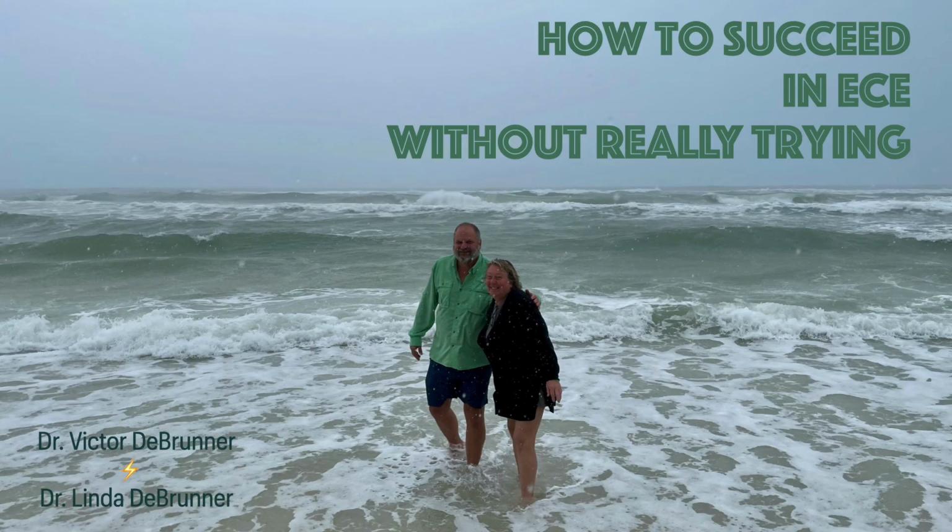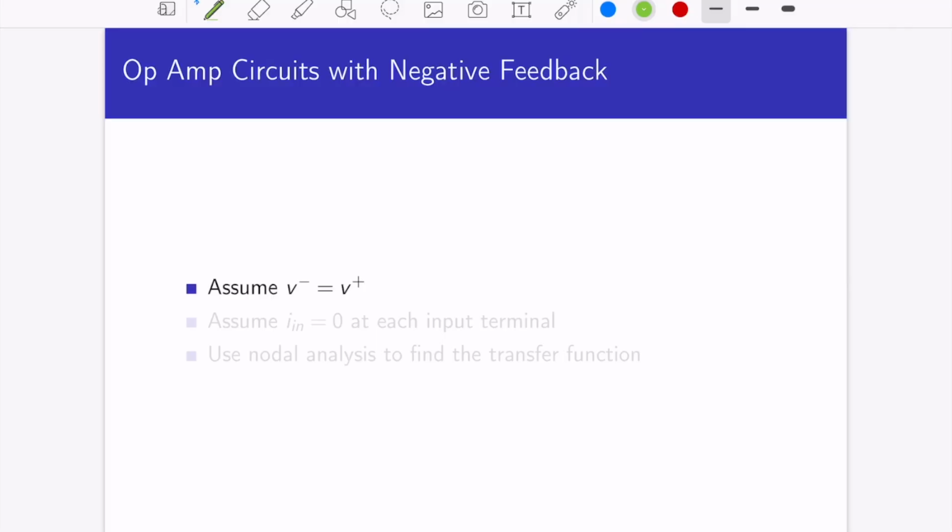I'm Dr. Linda DeBrenner, and in this video I'm going to review some simple, useful op-amp designs. Recall that for op-amp circuits with negative feedback, we can make several assumptions. First of all, that the voltage at the inverting terminal is equal to the voltage at the non-inverting terminal. We say that as V minus is equal to V plus.